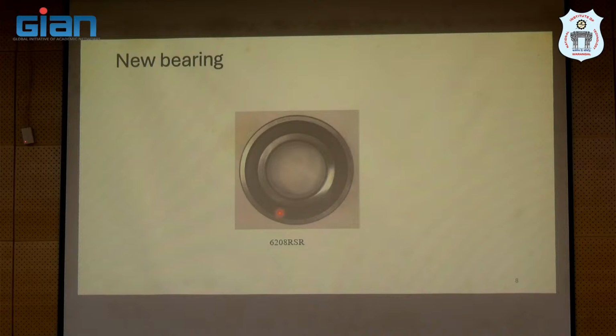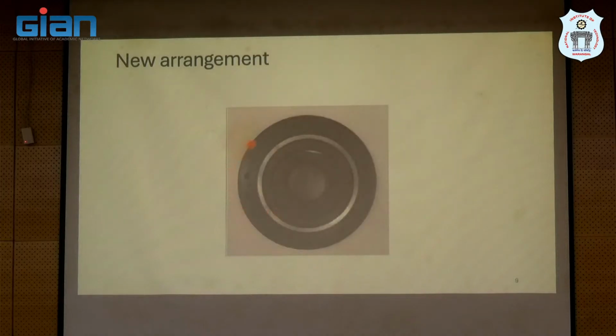If you have another type of bearing, you may have to lubricate it frequently, which is not convenient. So what we will end up getting is an arrangement like this. You will put the outer bushing, the bearing, and then the inner bushing. And this entire arrangement will be going on to the end plate on both sides, and the shaft will go through the hole that is visible.